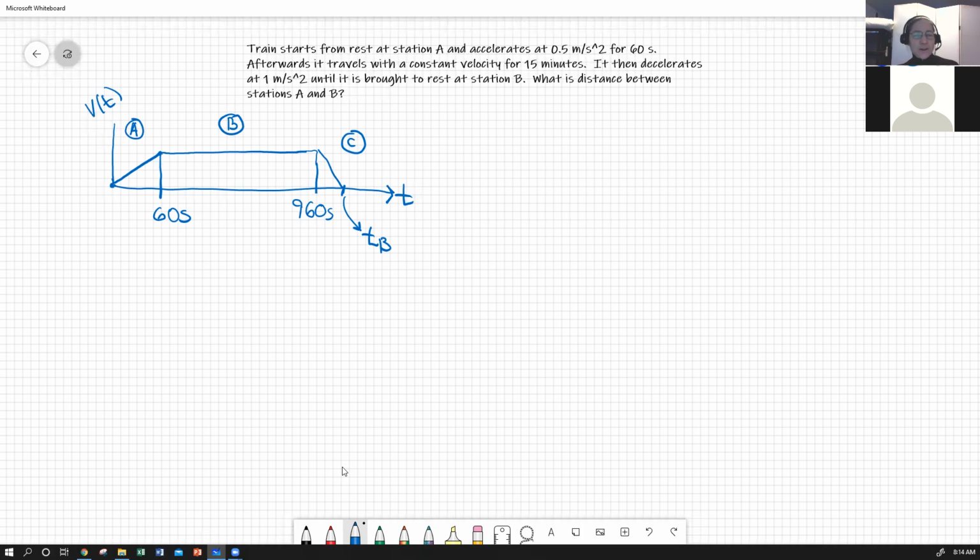This should start looking a little familiar to those of you who've done shear and bending moment diagrams. This is totally analogous to distributed load, shear force, and bending moment, by the way, except we're doing time rather than x. I found it's easier to just calculate distance for each region and set things up with a start time that's appropriate to each region rather than working out time offsets for the start and stop. I found that's a really easy way to end up making a math error. So I'm just going to tally up each region by itself and get the distance for it.